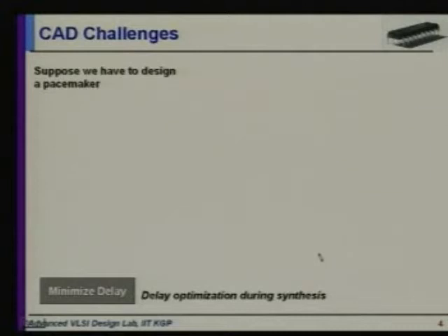What is the delay in the logic? The number of logic stages that you have, right? That is a combinational delay. So if you have a 5-stage circuit in which you have 5 layers of gates, then the delay is proportionate to that. And then there is a sequential delay also. In how many clock cycles can I perform this multiplication?